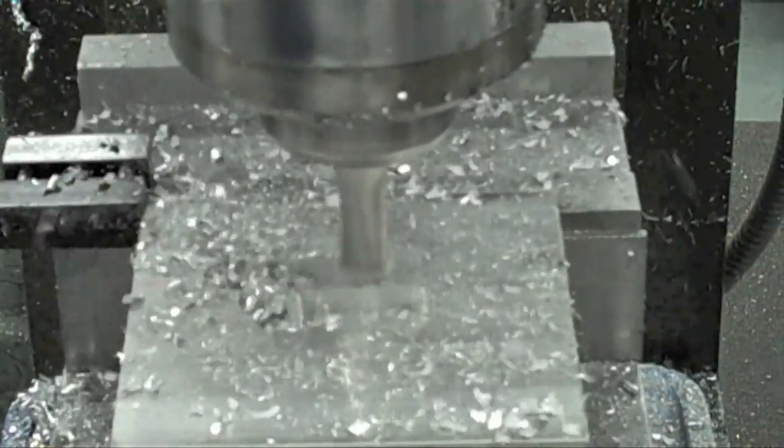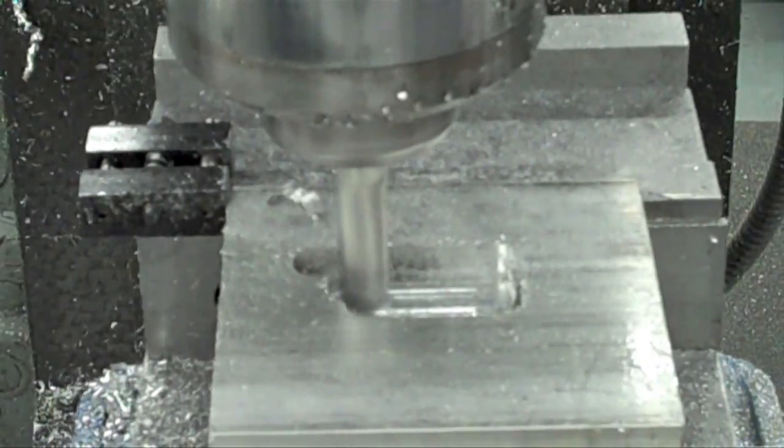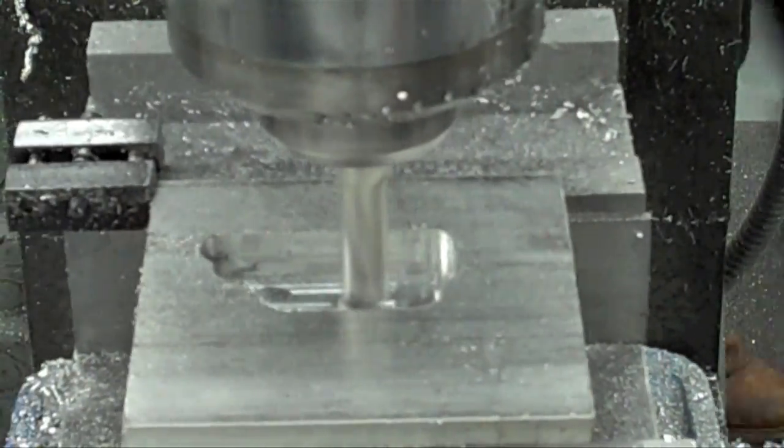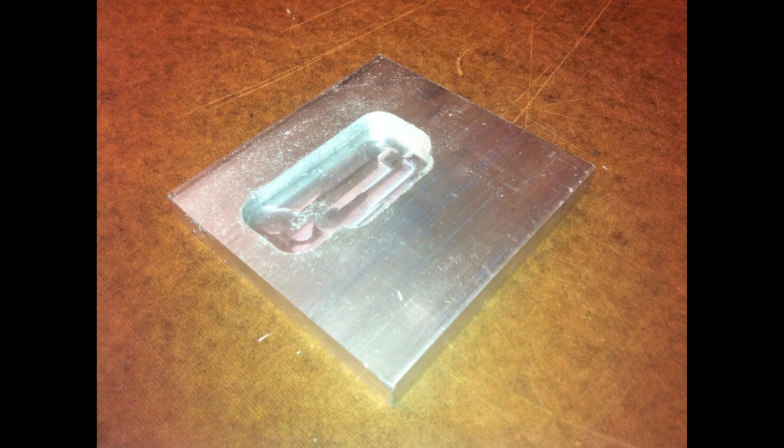Small corners can be made by using smaller and smaller mills, but this means more tool changes, slower feed rates, and more time spent machining. And eventually, a practical limit is reached, where the tool cannot be made smaller without breaking. This is an important factor to keep in mind when designing for manufacture. Since we are using a 1/4 inch mill to machine the pocket, the radius cannot be smaller than half the diameter of the tool, in this case, 0.125 inches.